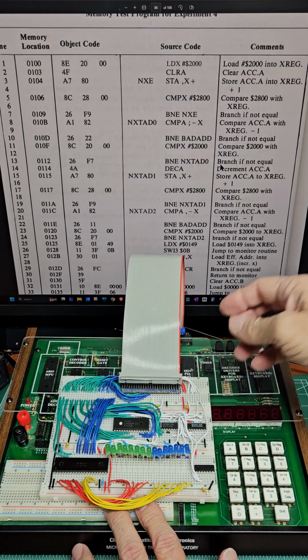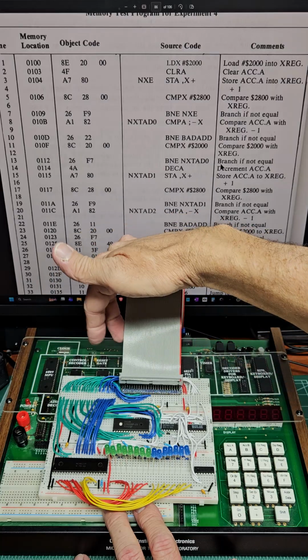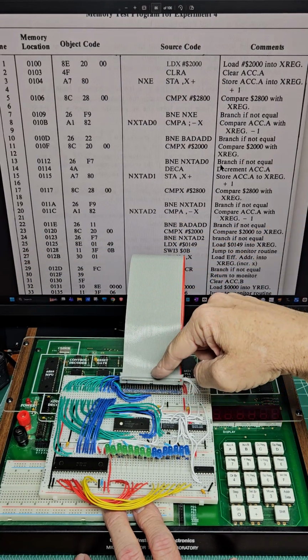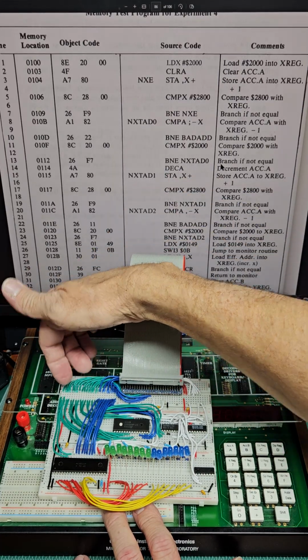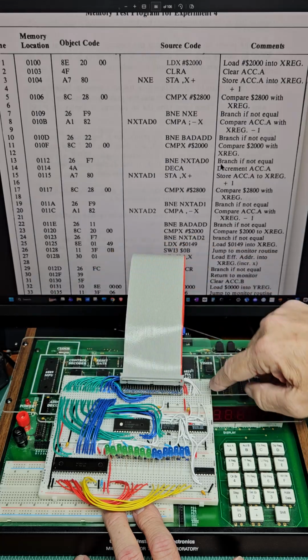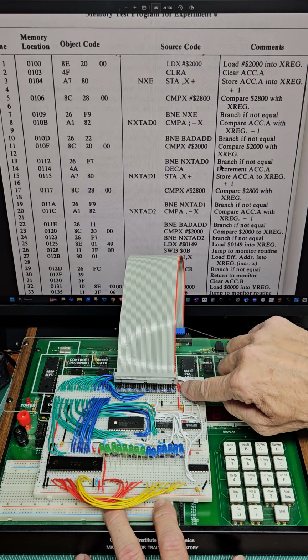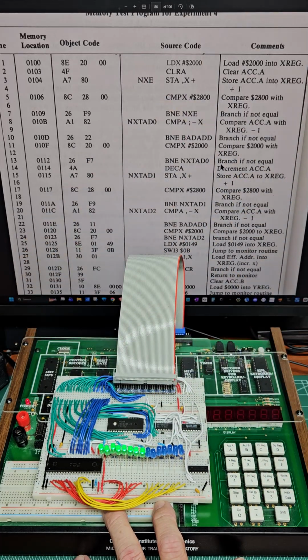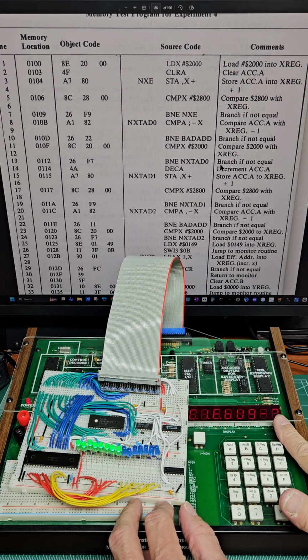And then what I did when I broke all these pins out, I broke them out on this one breadboard. So I got this one breadboard pretty much just to break out this connector. So the green is for address lines, the blue is for data lines, and the white is for control bus. And then the red is for power, and then the black is for ground. So I'm going to turn this on. And it comes on fine. Still running like it should.